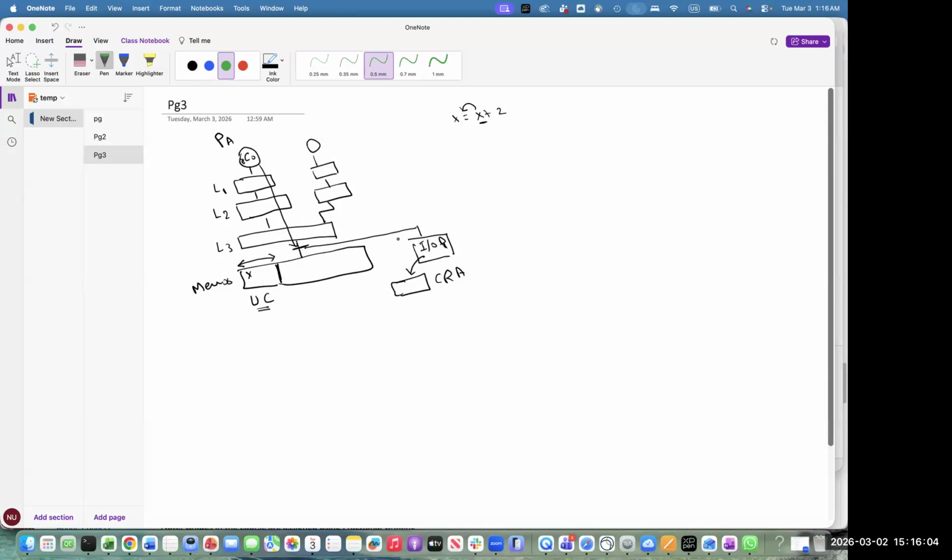Now just assume that for this control register A, the defined cache behavior was not uncacheable but was write back. If it was write back, and my process A, or my software, wants to write some bit pattern into this control register A, it will first issue a request for it, right?